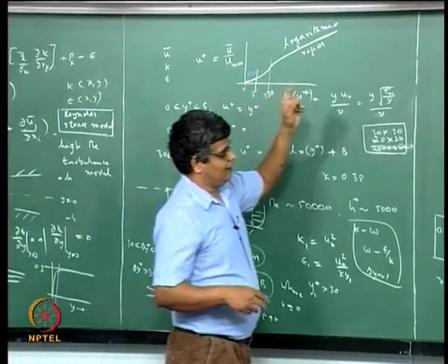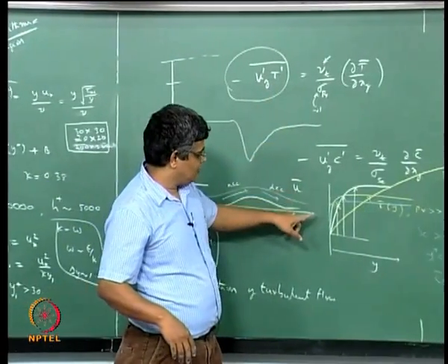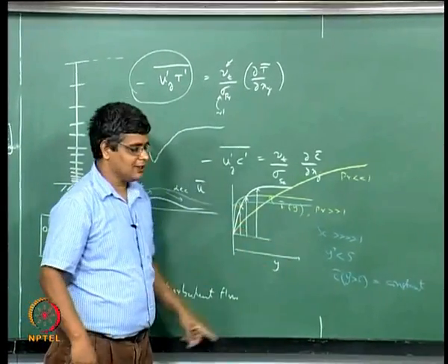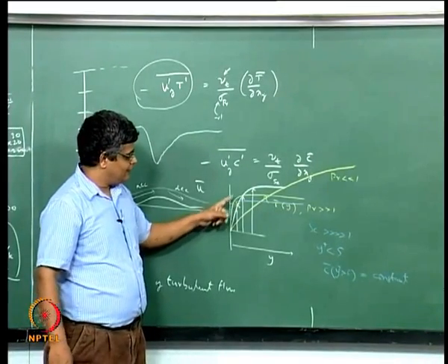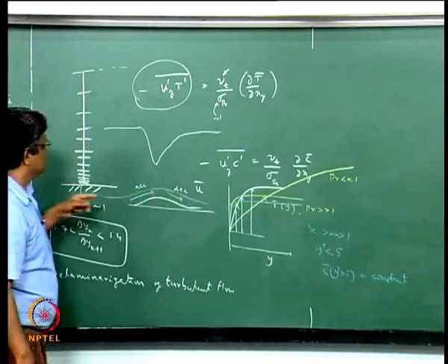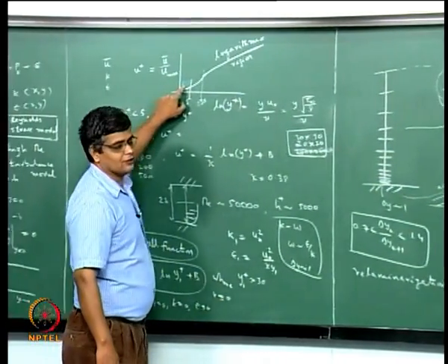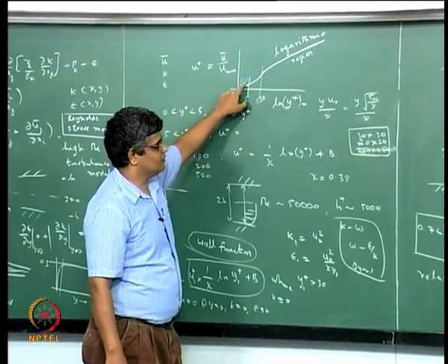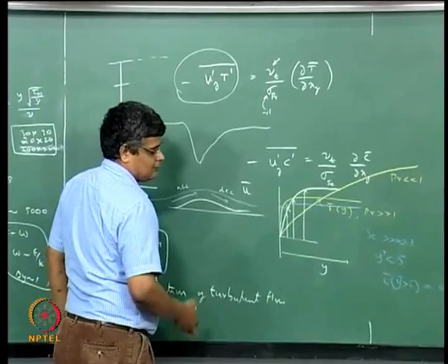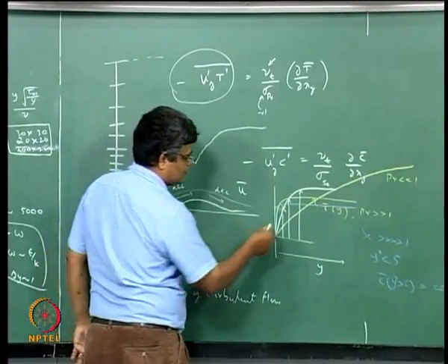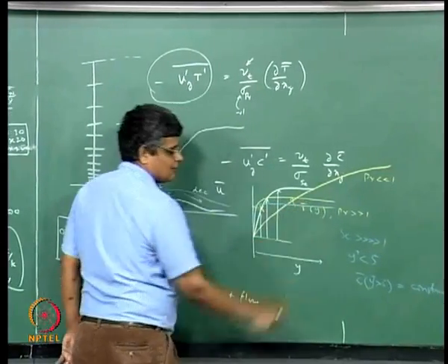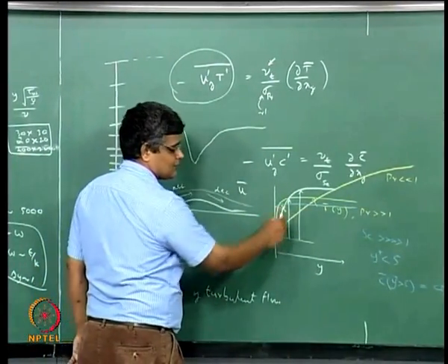So that means that in the case of turbulent diffusivity of the species for a Schmidt number which is much greater than 1, in reality there may be some effect of turbulence, but you are imposing no effect of turbulence here. So this is something that we have to consider, and as per your wall function, there is no further variation of concentration profile within this region. So this leads to some discrepancy.